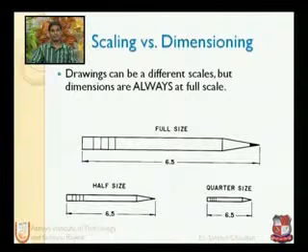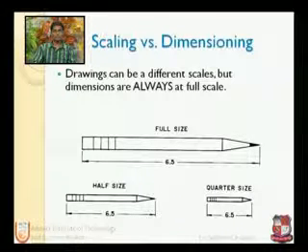Scale is always selected by the required space or the required layout. If we have limited space, we are not going to use the larger drawing. So we can see here, if the pencil scale is reduced further, for example quarter size, the dimension remains the same. So scaling versus dimensioning, it is important to remember that a drawing can be at different scales, but the dimensions are always at full scale.